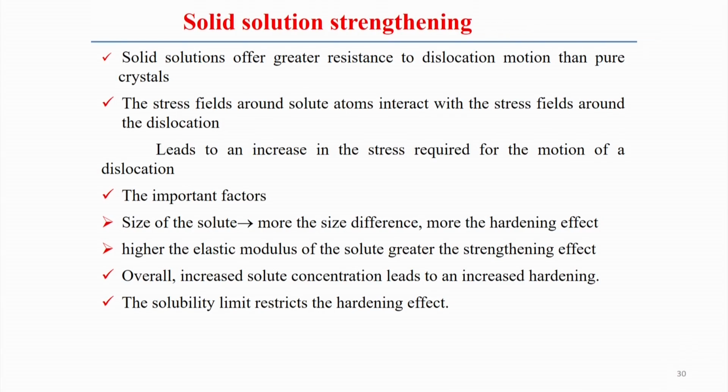But in an alloy or solid solution, the presence of interstitial and substitutional atoms restricts the dislocation motion, so definitely that imparts some amount of strength. Now the stress field around the solute atoms interacts with the stress field around the dislocation, which increases the stress required for further motion of the dislocation.